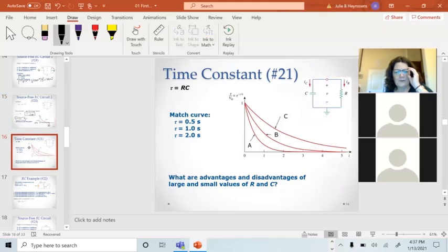One more thing I want to talk about before I get into my general method. The different time constants. Now, A settles a lot faster, and that actually means I have a shorter time constant because it's going to take roughly 5 time constants to settle. So this is settling in 2.5 seconds. It's getting down to 1%.